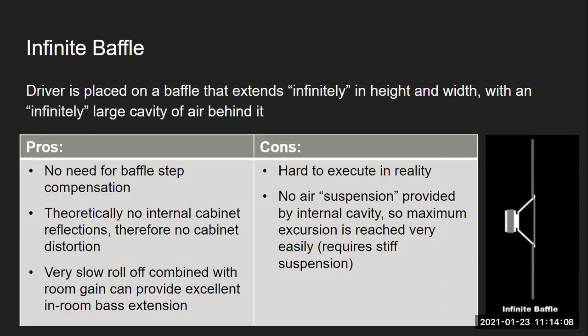But because they're being played omnidirectionally, the energy is being dispersed throughout the entire room. So it actually tends to sound like there's less output because it's not all being reflected forward towards the listener. So you have to do something called a baffle step compensation. You have to either cut the high frequencies or boost the low frequencies. Typically, it's cutting the high frequencies if it's a passive design. So what's cool about infinite baffle is that doesn't happen.